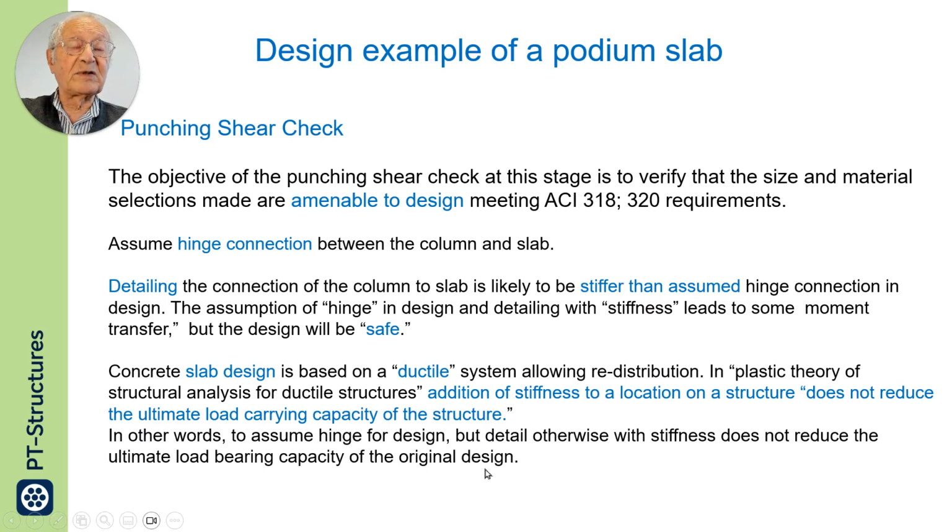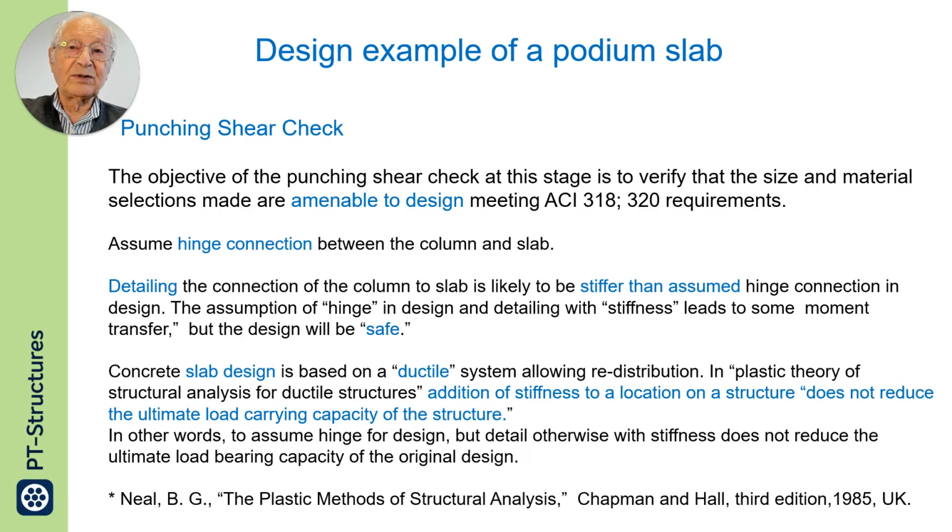If the design was based on hinge, but the execution was stiffer than hinge, the load-carrying capacity of the structure will not be less than what was designed for. This is one book which gives you the theory of plastic design and the argument for it. There are other books too.